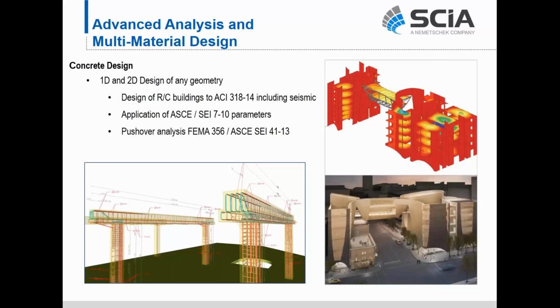So also speaking in line of multi-material design, we can do concrete design. So we can also, again, do 1D and 2D design in any geometry. So we can design reinforced concrete buildings to ACI 318, including seismic. We have other applications to ASCE 7. We can perform pushover analysis.